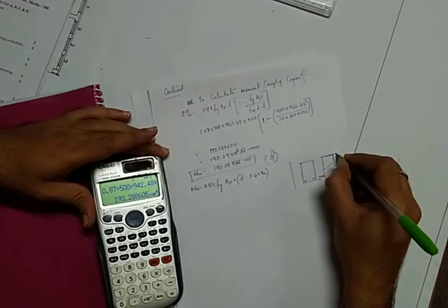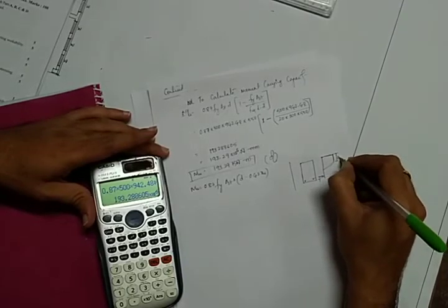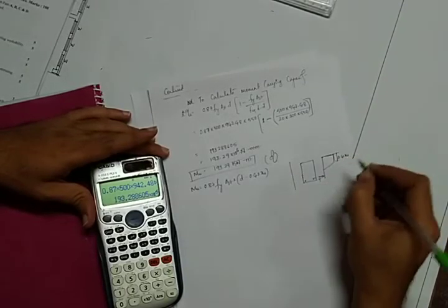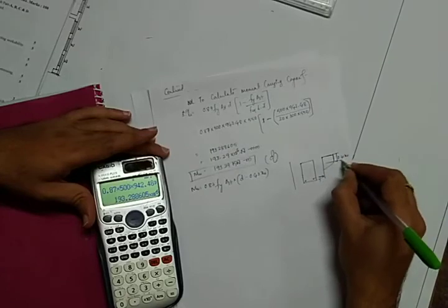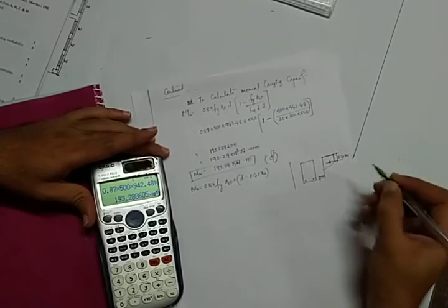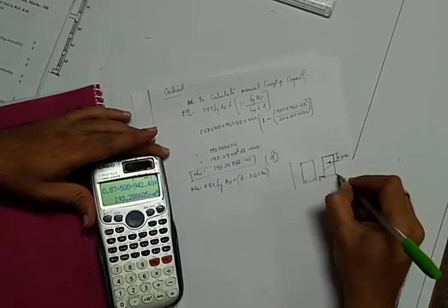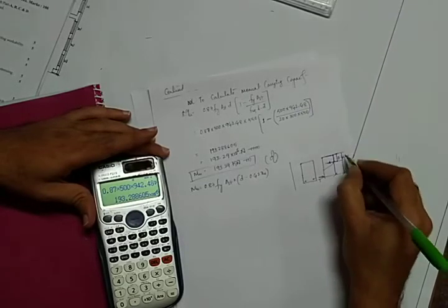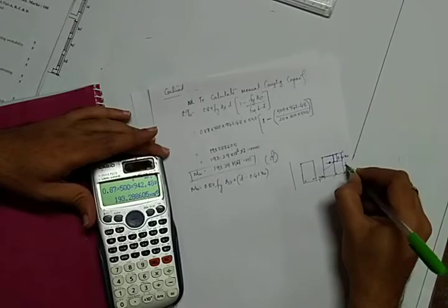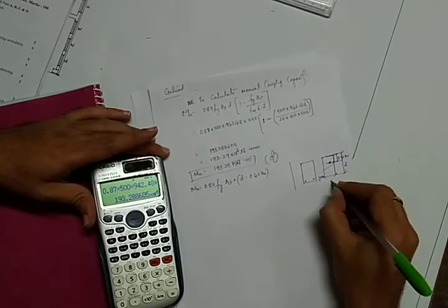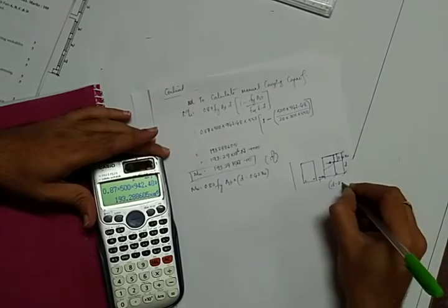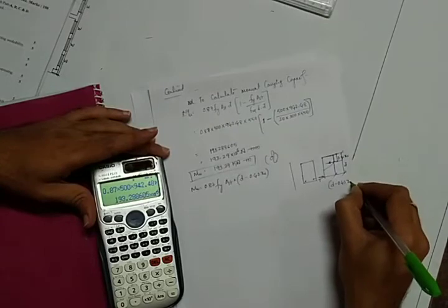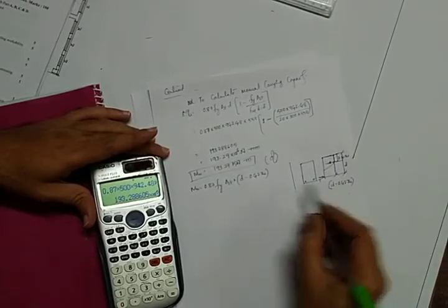I hope this is known to you. This will be 0.42 xu, and here the compression force is acting. The distance between these, from here it will be small d, that is effective depth, minus this. So the distance is d minus 0.42 xu. This distance is written here.